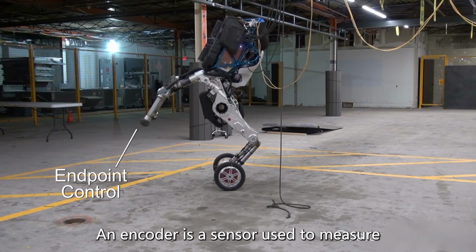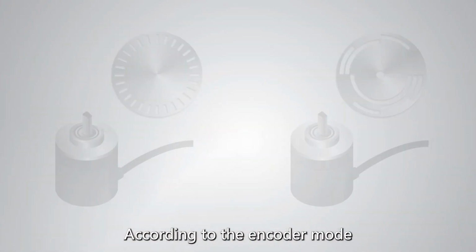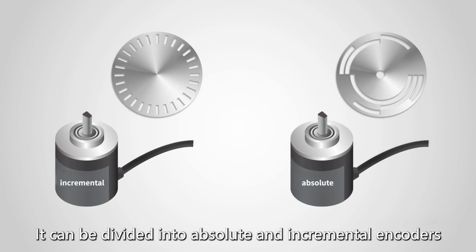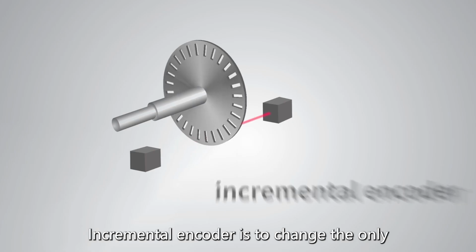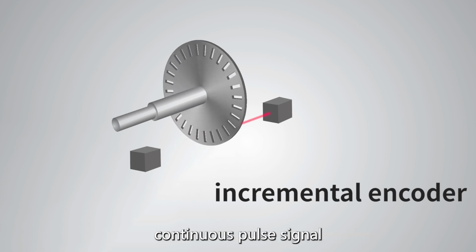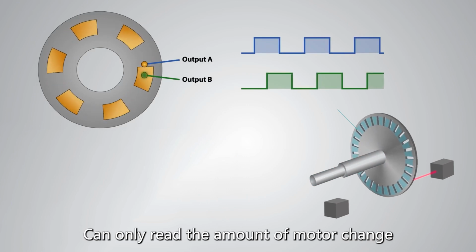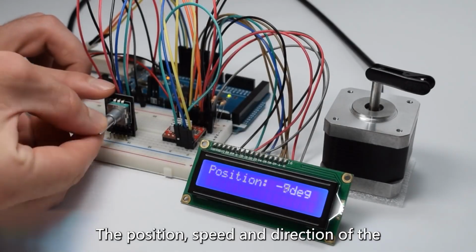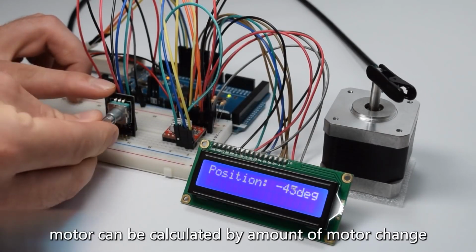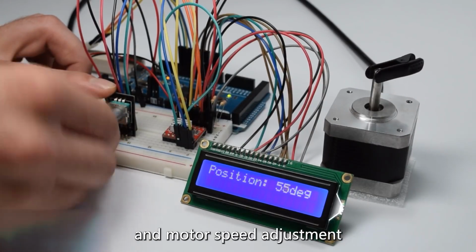An encoder is a sensor used to measure mechanical rotation or displacement. According to the encoding mode, it can be divided into absolute and incremental encoders. An incremental encoder changes the motor movement information into a continuous pulse signal. The number of pulses indicates the displacement, and it can only read the amount of motor change. The position, speed and direction of the motor can be calculated from the amount of motor change, which can be used for real-time monitoring and motor speed adjustment.